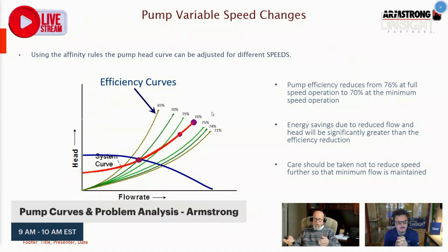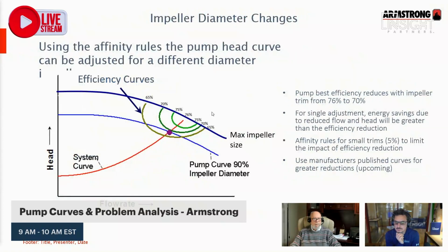Now the other thing everybody has to pay attention to is minimum speed on a pump, and every pump's a little bit different where its minimum speed has to be. As a general rule, somewhere between 20 and 30% is the minimum speed. Some pumps it's a little bit more, some pumps it's a little bit less, but keep in the back of your head that that's not a hard and fast, got to be this. It can change a little bit depending on the pump.